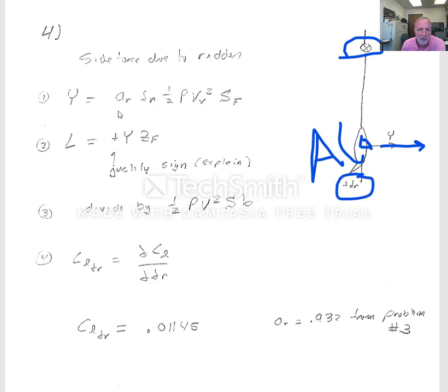And so the rudder effectiveness times the rudder deflection gives you the coefficient side force, and then you multiply by Q bar and the area of the fin to get the side force. The moment, this is a rolling moment, is just the force times the moment arm. Make sure when you do this derivation you justify the sign based on where the force acts and where it is relative to the CG and which way is positive or negative.